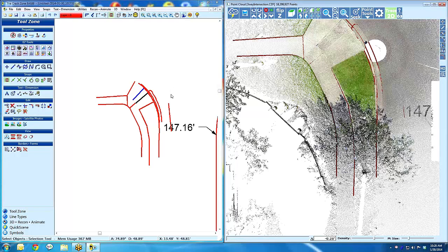That's another little trick. If you're working indoors and doing a crime scene, start out by doing a top-down view and do everything in 2D, and after you've zeroed out your ground plane, that ground level adjust thing, that way you can get the outline of your room without any errant 3D glitches, and use 3D Builder in our program to give a wall height, and then you can just go back and forth. So you can switch back and forth between this mode.